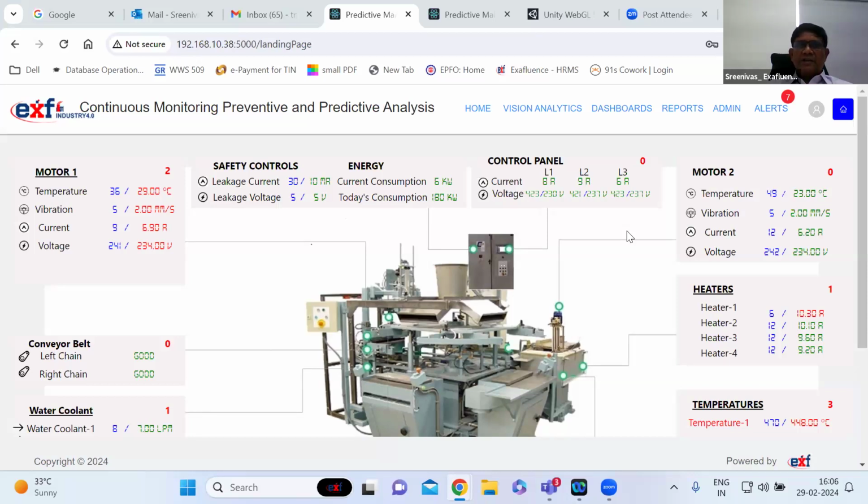So what we are doing in prevention is basically continuous monitoring of a motor. By observations or by law, we have a fixed temperature, fixed current, fixed voltage, and fixed vibration of the motors, fixed in the sense of standard values. We get the data from the PLC: what is the motor's present current, vibration, torque, and voltage, and we completely observe them.